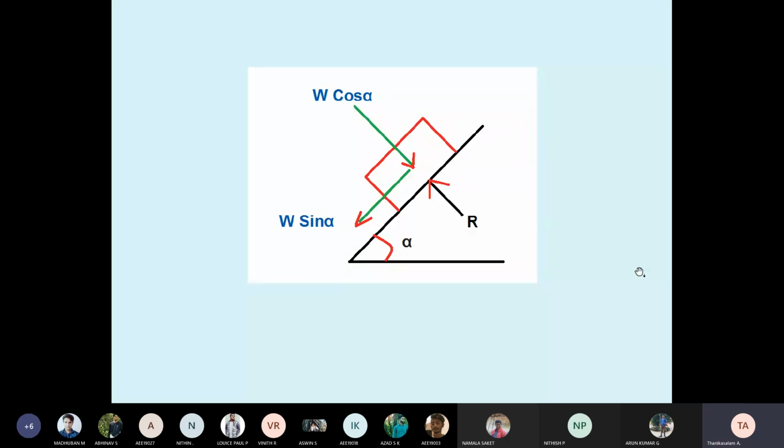So this is the inclined surface first concept: we resolve the weight in the xy direction. The other things come next. If the body is moving upward, friction is downward, like that. Remember, students, for any block on an inclined surface, W cos alpha and W sin alpha. Then you think about other things later.